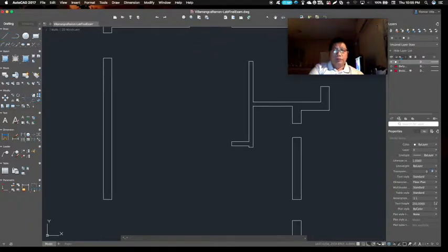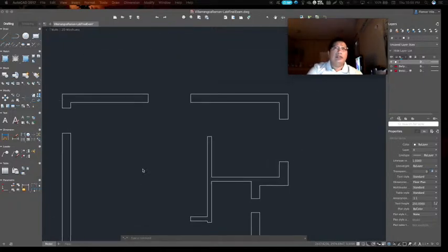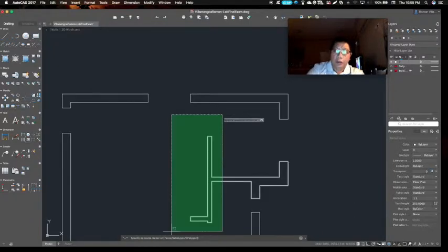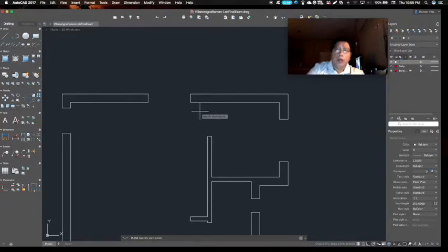So the first wall I'm going to make is this small wall here, which we can draw using P line again, from this line going to the left by 600, then going down at 300, then going left at 150, and then going up by 300 again, and then closing the polyline.